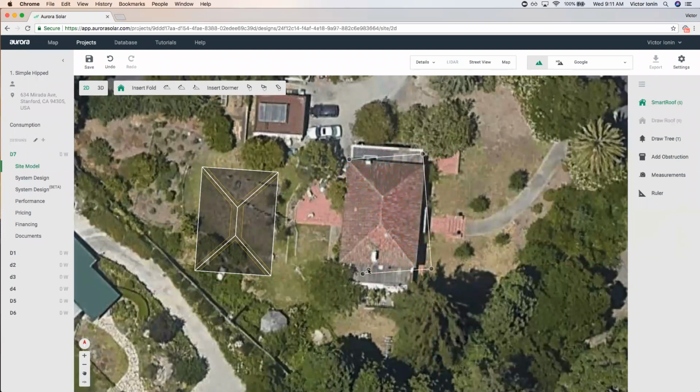Or another option is if you hit escape, you can click on this unfinished drawing and click on the pencil button at the bottom. This will bring you back into the edit or the draw mode, and while in here, you can go ahead and try and line things up. Once you line it up, you may want to continue the drawing, and the way you do that is just by double left clicking a node, and you can complete the drawing.